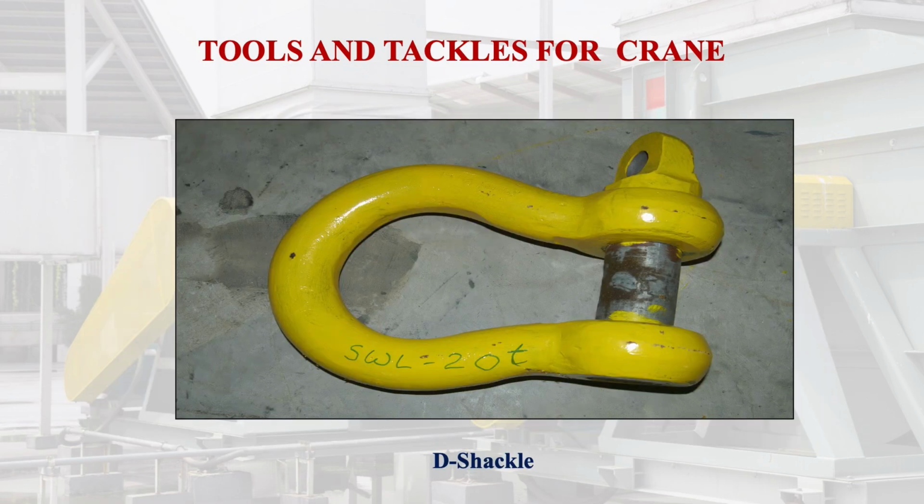This is also a D-shackle of 20 ton capacity. The operator thinks what may go wrong in this D-shackle. He will see it polished, daily he is looking at this D-shackle and sees nothing abnormal. But with the passage of time when we use the D-shackle, its opening starts expanding. If the opening starts expanding, what does it mean? That means it is subjected to fatigue failure, and sometimes this may result in a serious accident. Another thing in this D-shackle is the pin.